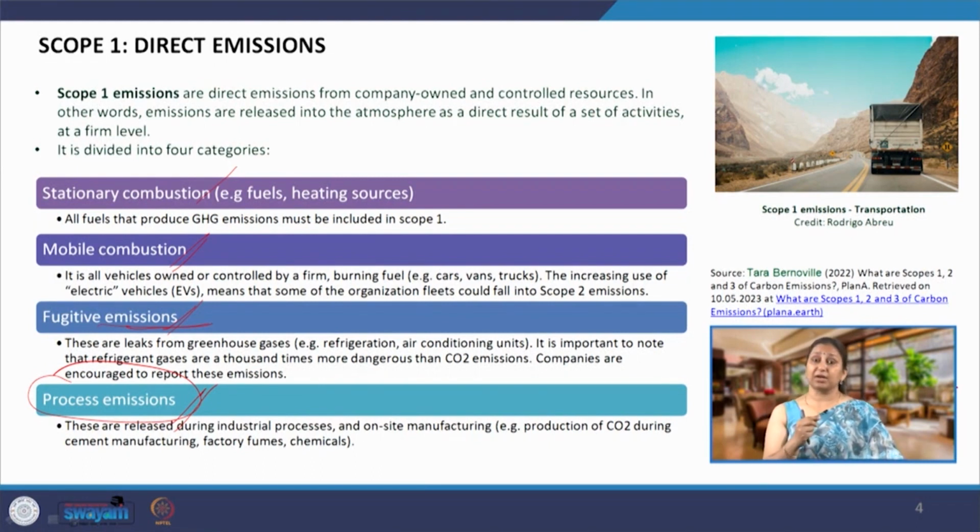And how do we know that? How would companies know that the gas has leaked? Because there is a certain pressure that has to be maintained and we know the total volume. So, in the maintenance process, to continue to run the plant at a certain efficiency, these pressures and the volume of the gas that is inside the system in a closed loop is constantly monitored, and we need to refill the gas.